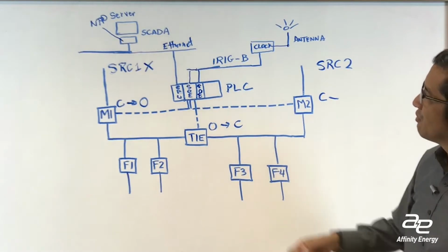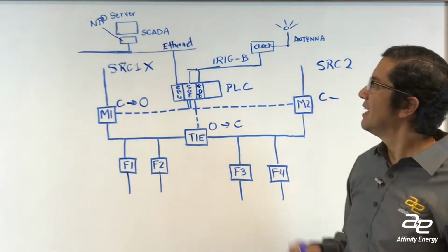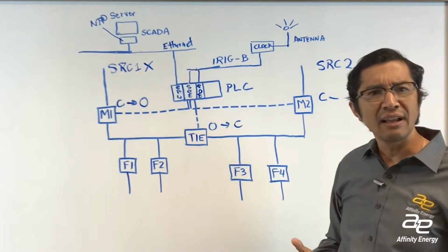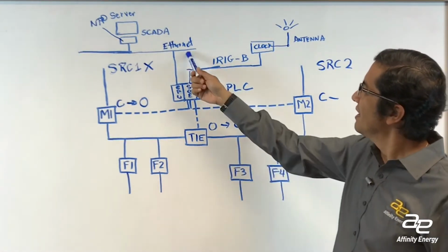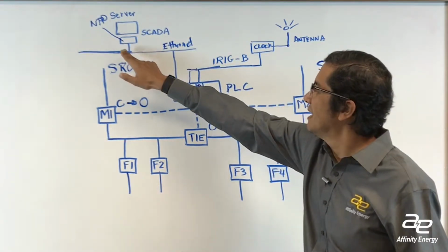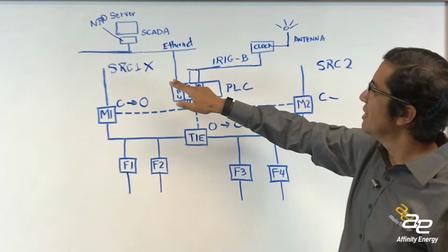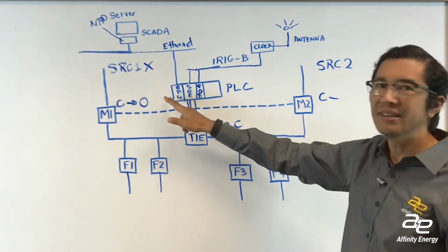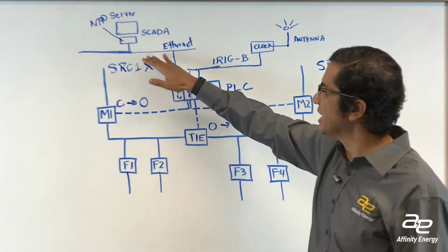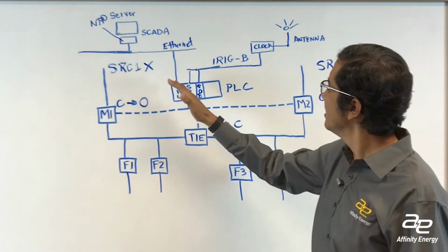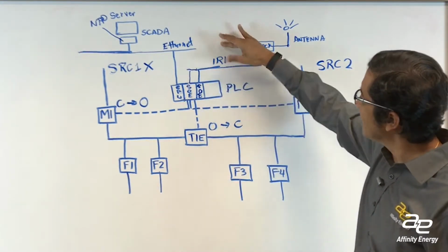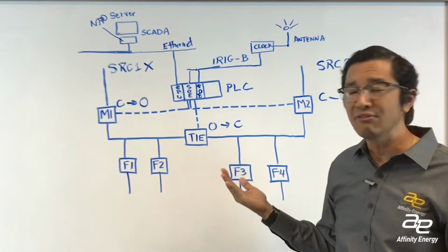But the big difference, and the reason why you wouldn't want to use this in the electrical industry, is number one, Ethernet is what's called non-deterministic. So when you send a message out by Ethernet, you don't actually know when it's going to be received by the CPU. There's going to be what's called network latency. There could be a collision that occurs and then a reset. So in order to have synchronization of time occurring, that's why the IRIG-B standard was developed.